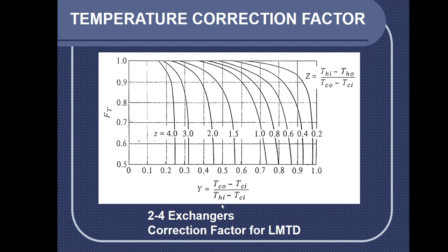It requires that your temperatures for all your streams should be known. This method will not be able to give you the actual amount of heat transfer rate when either one of the four temperatures is unknown. So you can determine one if unknown and the rest of the three is given by using energy balance. That is, the amount of heat from the heating medium is equal to the amount of heat absorbed by the cooling medium.